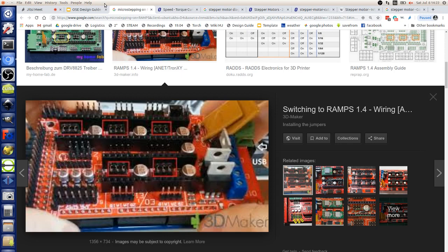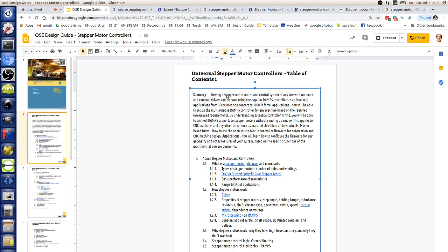The speed, right, you set the speeds in... The Arduino has an interrupt to ensure very precise timing on the operations, and I think some of them are high frequency. Yeah, you just give it the speed. I believe after you declare a speed, the Arduino sets the speed, and the stepper driver actually executes that speed by the appropriate timing sequence required to get that particular speed. So that's kind of the insight into how that works.